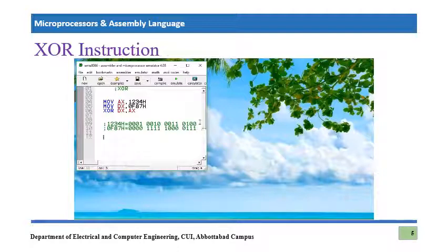So I'm going to exclusive OR. What is going to happen? Let's see. Remember how exclusive OR works. Whenever we have two different inputs, it will always produce a 1. If you have similar inputs, it will produce 0. So 0 0, similar inputs, result will be 0. 0 0 similar inputs, result will be 0. 1 0 result will become 1. Okay, next, 1 and 1, inputs are similar, so it is going to be 0, and then 1. I hope you can do it yourself, so I'm just doing it. 1 1 and 0 0 1 1.